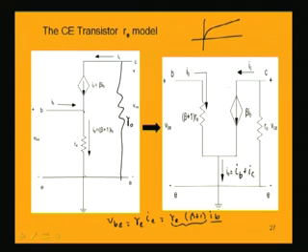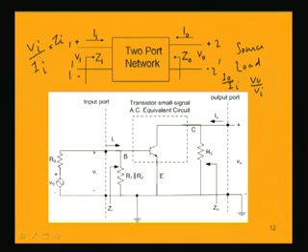So, now this circuit is the common emitter transistor equivalent circuit, which will be used in the AC equivalent circuit, and the further analysis will be now done for finding out the relevant parameters like input impedance, output impedance, voltage gain, current gain, all these will be found out. So, now this AC equivalent circuit, whatever we discussed in the beginning, will be having this transistor incorporated into it by this equivalent model. So, instead of the transistor's physical model or symbol, we will be incorporating that model which we have just now derived, replacing this transistor by this equivalent model.